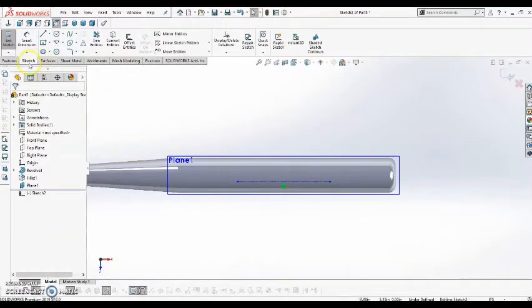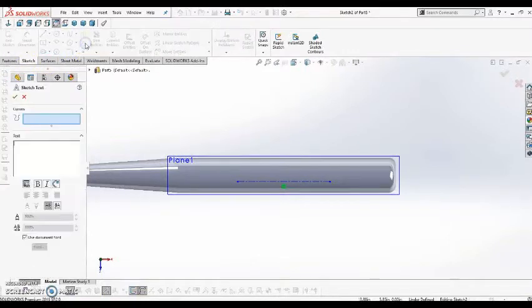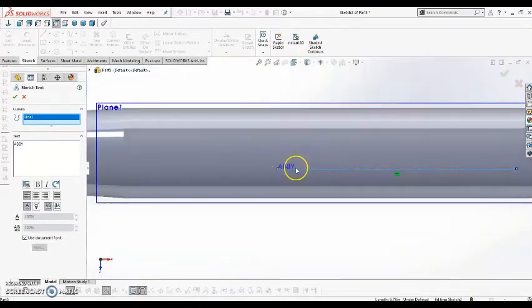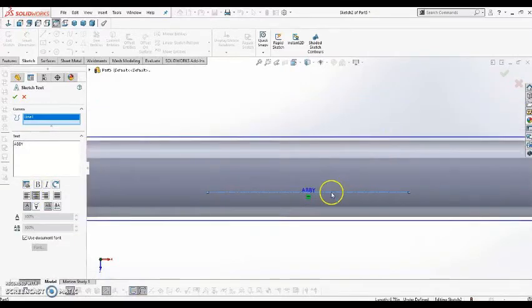So now within my sketch window, I can go up to the text tool, and for the curves option, I'm going to select the dotted line that I just created, and I can go ahead and type in my text. It's very small, but it does appear. So within here, we can change the alignment of it, so I'm going to move it to the center. And then we can also make it a lot larger.